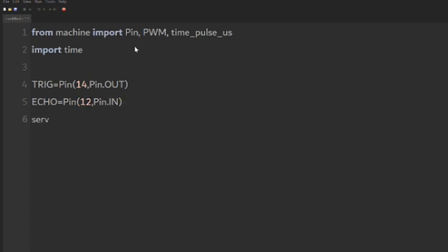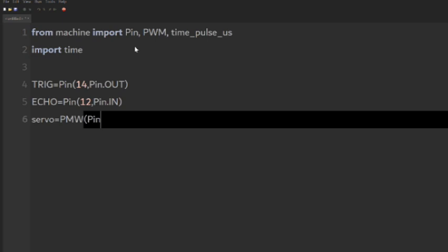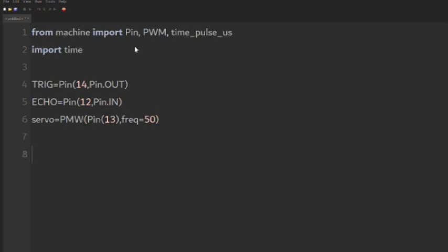And the next pin is servo. It is a pin of servo motor and it is given to the pin number D7 of ESP and it is working with a frequency of 50 Hz. Then we are starting this toll gate by making it initially closed. We can close it by putting the duty like 120. We are also taking this command called gate open.